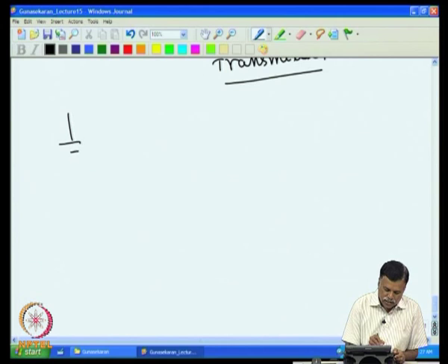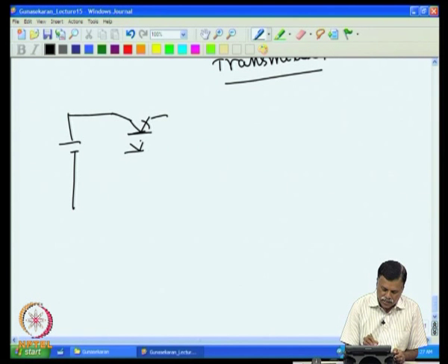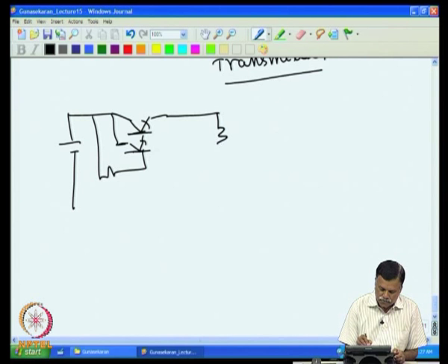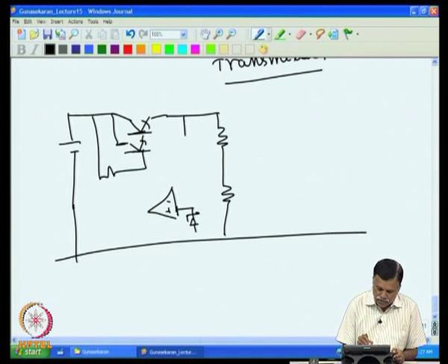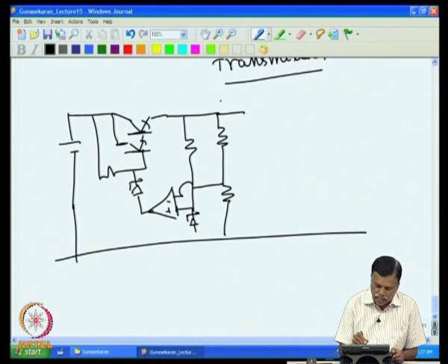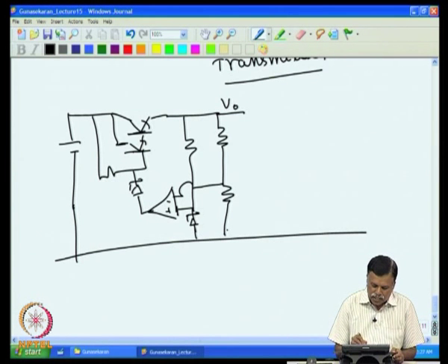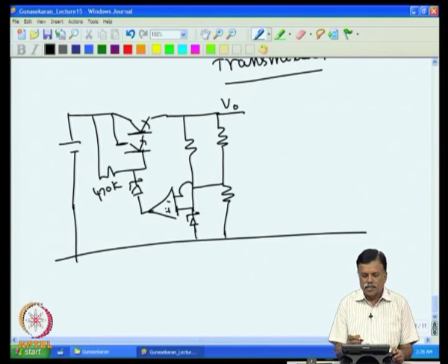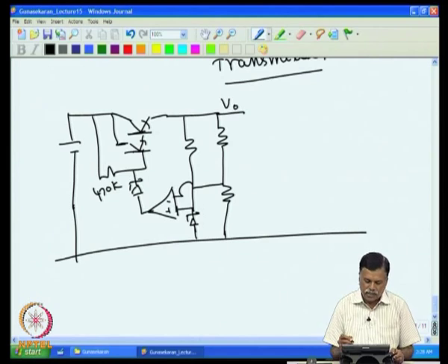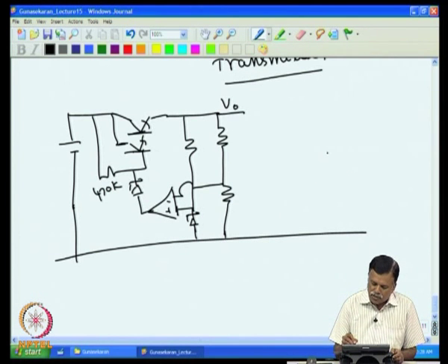So, here we have the voltage source, and then we had the regulator that consists of one Darlington pair transistor. This we had discussed in the previous class. So, we had the biasing resistance here, and then we had the output. The output voltage is taken, and then we had the error amplifier for the voltage regulator. So, this is the voltage regulator part of the current transmitter. We had a 470 K resistance here, and this is a Zener to give a startup current for that.